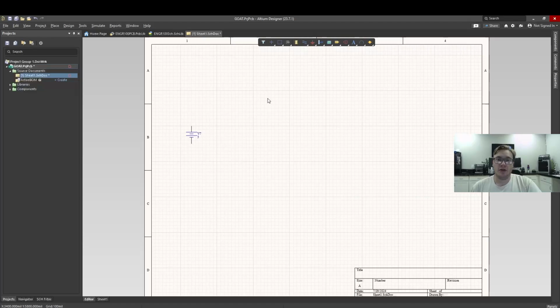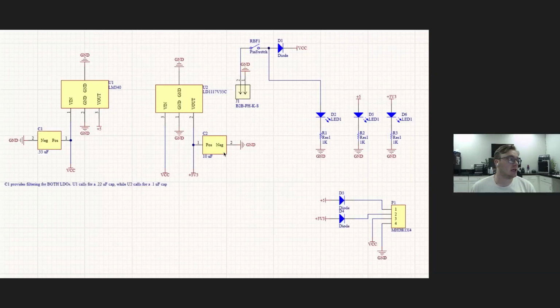And this is going to, on one side, be connected to what's called the ground net. So a net is anything, they're small red labels for Altium that show all of these things are connected. So if we go back to the slideshow, we can see this is the ground net connected to the battery. This is the VCC net.